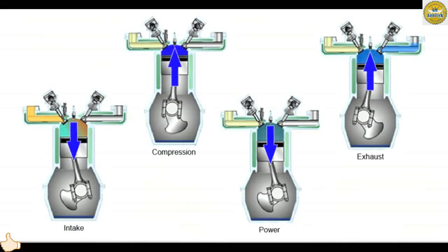The four-stroke system of operation consists of an intake stroke, compression stroke, power stroke, and exhaust stroke. One stroke is counted each time the piston moves the entire length of the cylinder. The term four-stroke engine is used because the piston moves up and down the cylinder 4 times in one cycle.